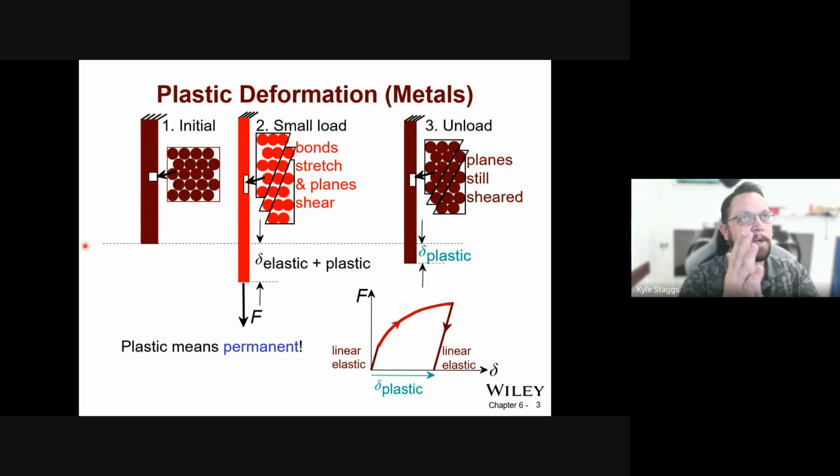Those planes are shearing, so you're moving a defect along those planes relative to each other, and they slip. So as you're adding force, these bonds become weaker and weaker between these layers, and they're able to slip, and that causes stretch in the metal.